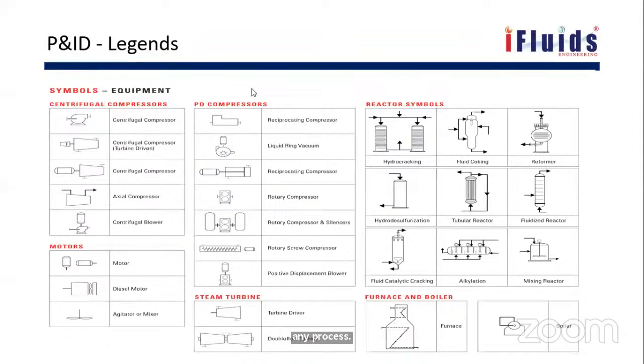So now, normally P&ID drawings are numbered in the order of the process, right from the start of the process to the end of the process. Following are the main parts. Drawing numbers and details of the project. And you'll have the graphical representation of the process in the form of vessels, pipelines, equipments, everything. It also has the details of all process and utility piping, details of instruments and control schemes. This we already saw. So all this will be available in the P&IDs.